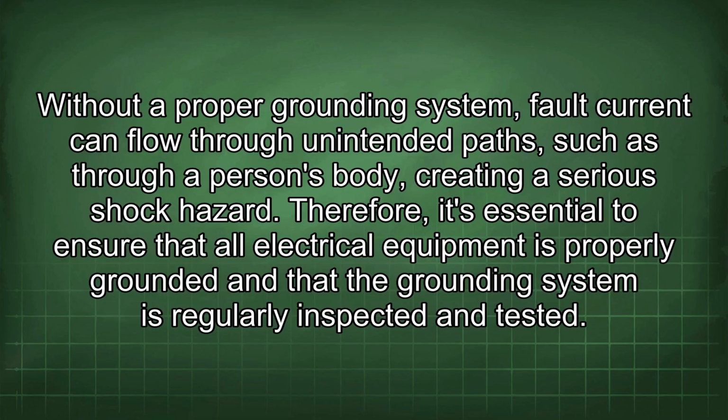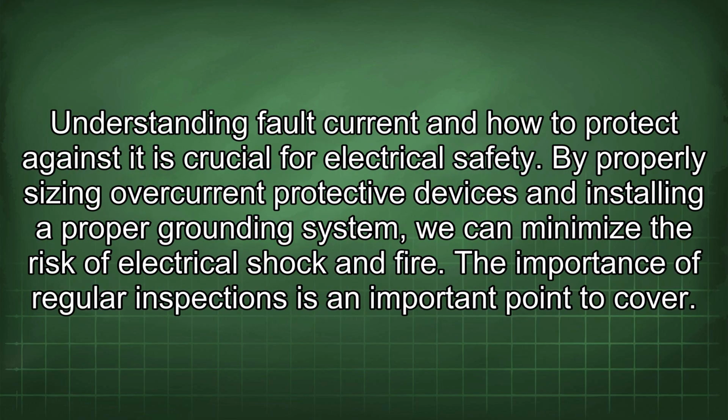Therefore, it's essential to ensure that all electrical equipment is properly grounded and that the grounding system is regularly inspected and tested. Understanding fault current and how to protect against it is crucial for electrical safety. By properly sizing overcurrent protective devices and installing a proper grounding system, we can minimize the risk of electrical shock and fire. The importance of regular inspections is an important point to cover.